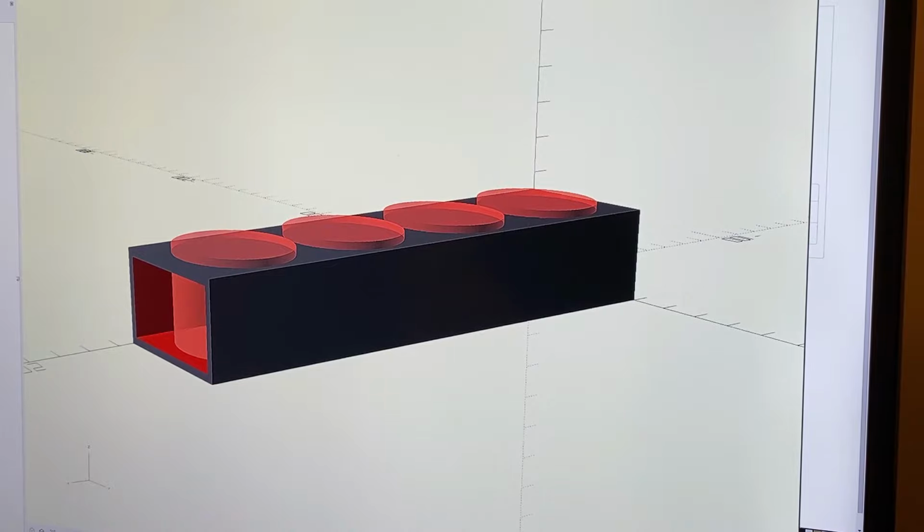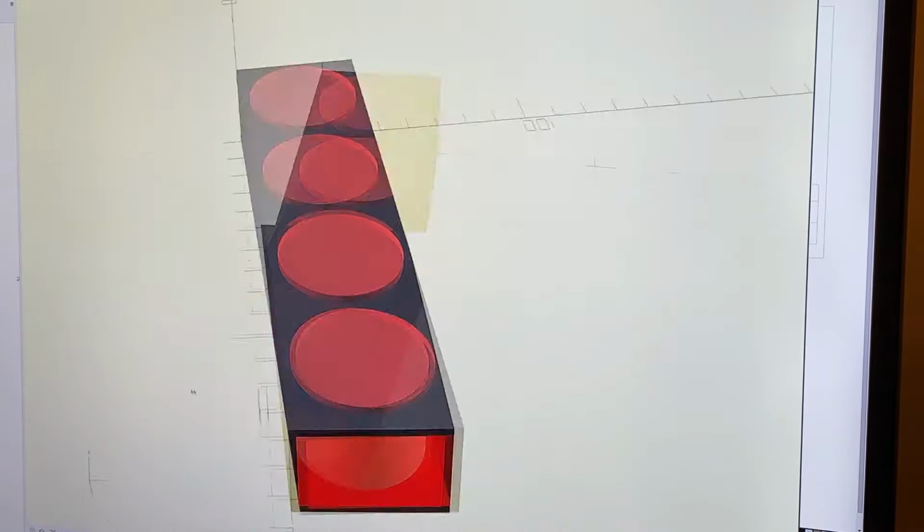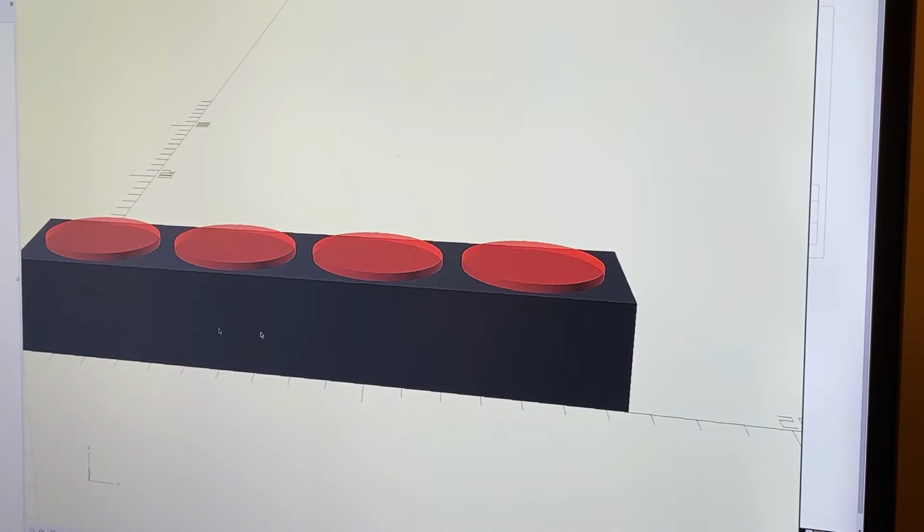Okay. The next step is that we want to mount this on a wall. So on the back side here, I'm going to add some screw holes. I'm going to do this about the simplest way I can think, which is to have a smaller hole and then below it a bigger hole. So the screw head will go in the bigger hole, and you'll slide the whole thing down and it'll rest on the smaller hole. So let's start with the left-hand side one.